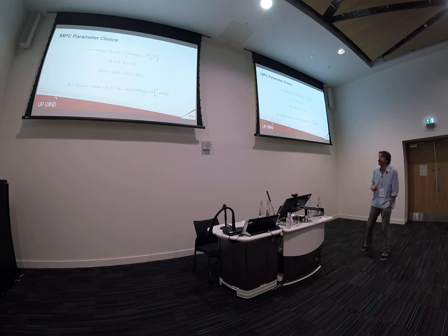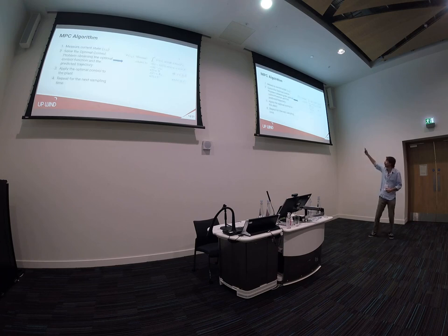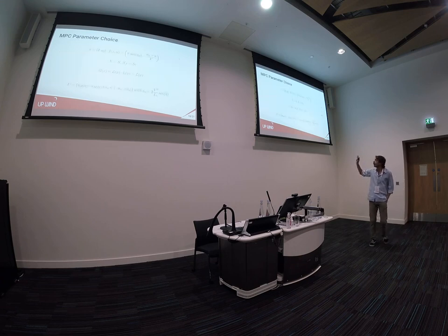In terms of MPC, a really important thing is to choose the parameters of this optimal control problem. So basically to define the cost functions, the state sets, etc. And here is basically what we've chosen. If you notice, for G and L, we basically used the Lyapunov function pair that was used to prove the stability of the basis controller. Okay? And why is that? Because this can also guarantee stability of the MPC term.